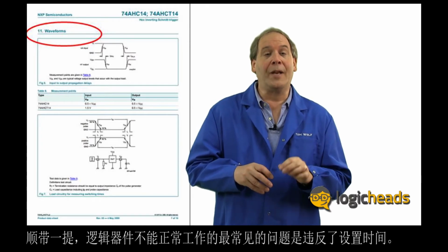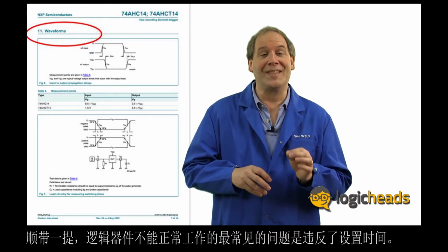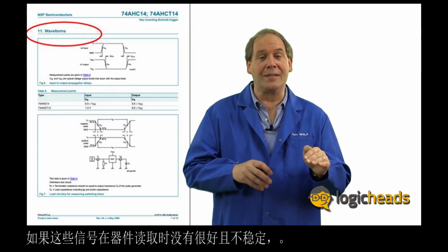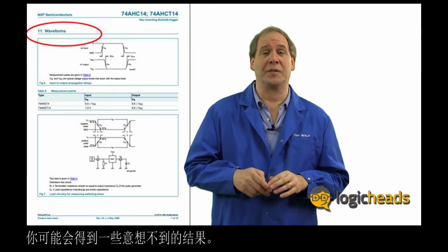By the way, the most common issue with logic devices not working properly is a violation of the setup time. If those signals are not nice and stable when the device reads them, you may get some very unexpected results. So check that first if your circuit isn't working.